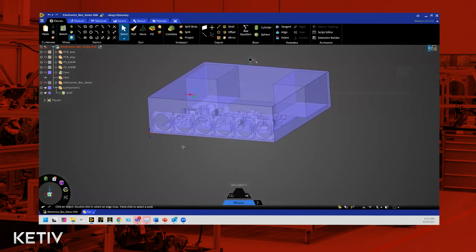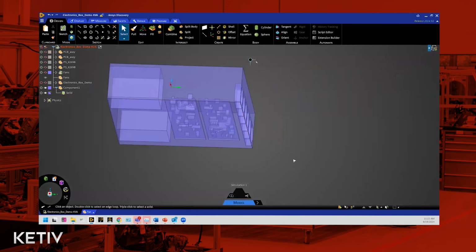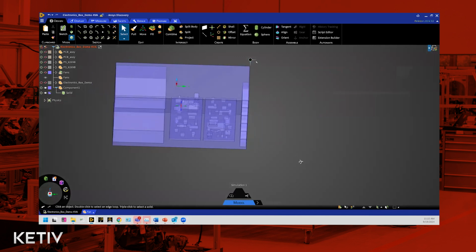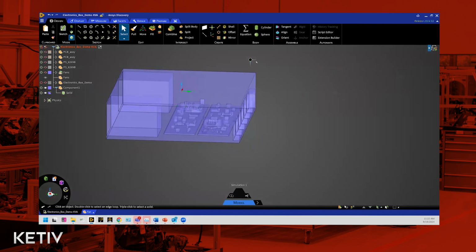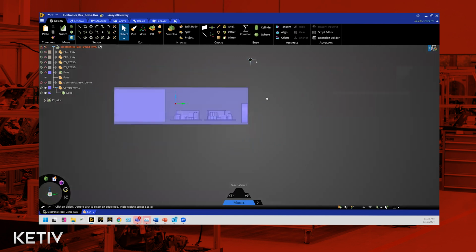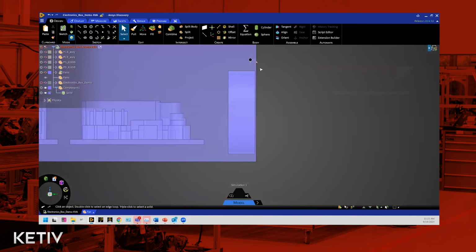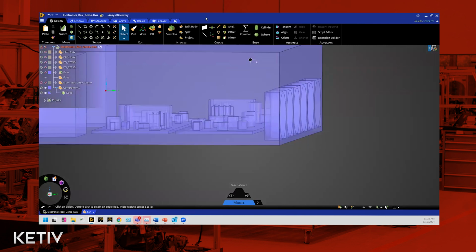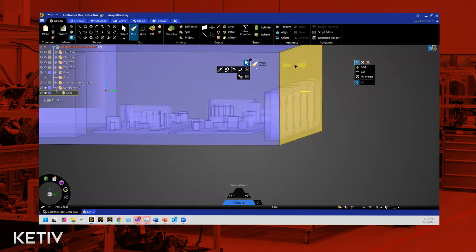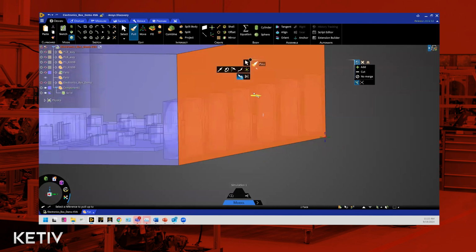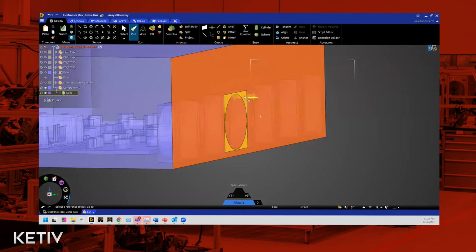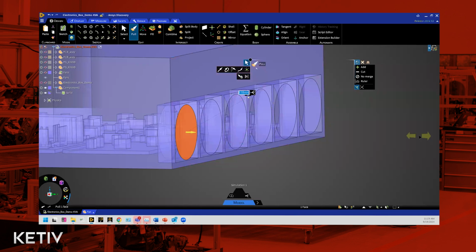And just to make sure that we have a boundary condition available on the fan body, we'll align this face with the intake face of the fan, okay? So let us pull this face up to this guy over here.